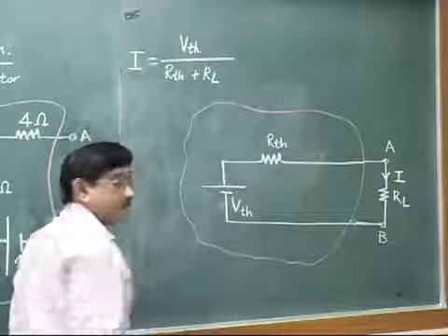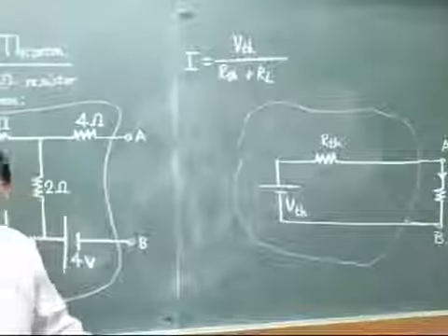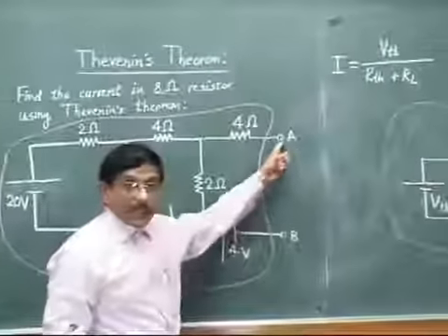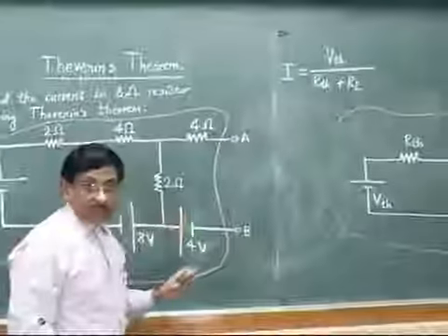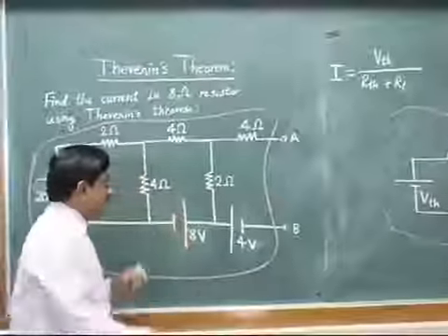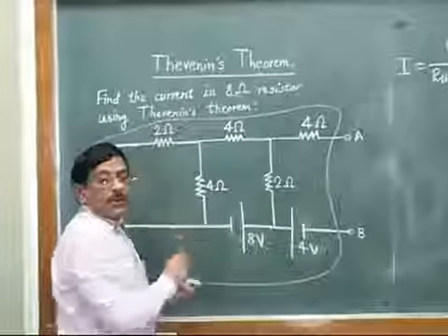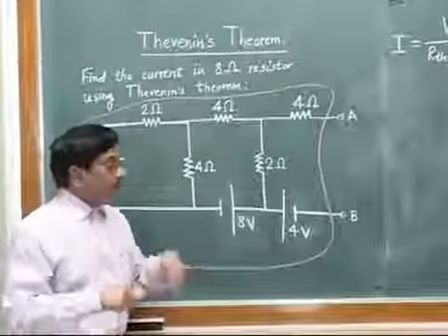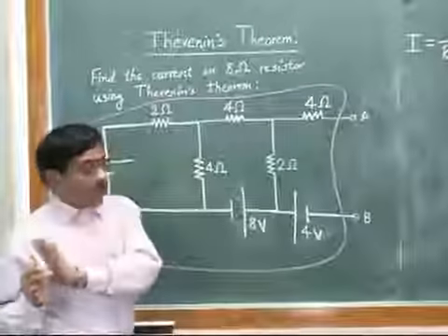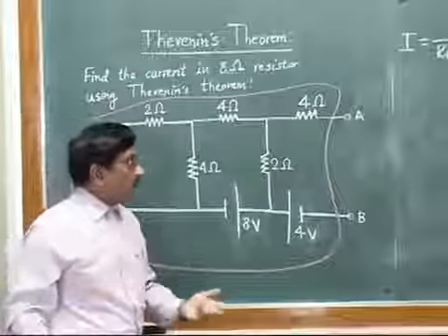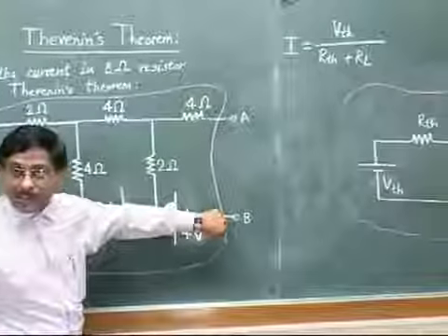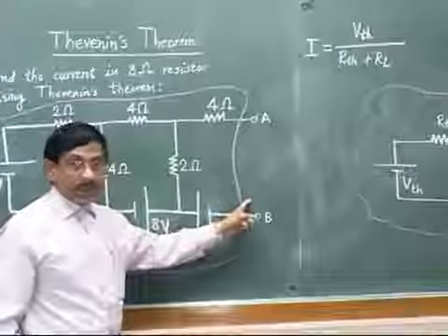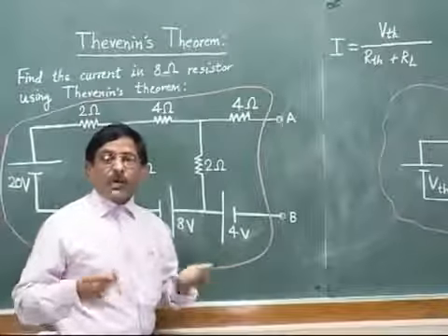So this is the simplest idea that Thevenin has suggested for finding out the current in the given load resistor. Okay, so simple central idea. Such a given circuit, we want to find out current in any given specific resistance. We remove the resistance, call it as a load resistance. Once we remove it, we get the two open terminals. Then across open terminals, we perform certain operations.